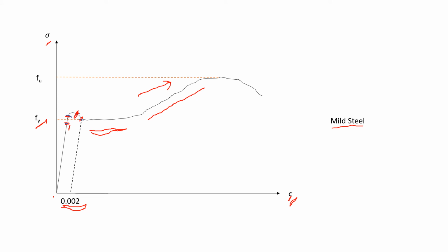As the metallic bonds first slip, they are sliding, and then at some point they resist each other. The flow of each element is resisted, and that resistance gains strength in the material as we increase the dimension too. That metallic bonding provides strain hardening, so the stress value increases as well as the strain value.